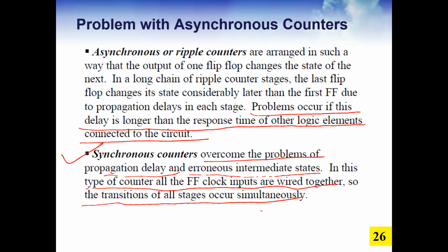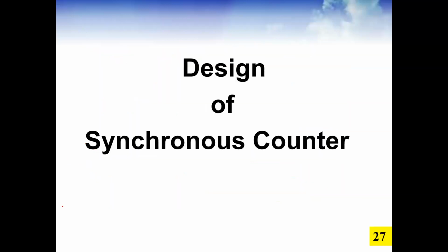Okay, next. In a synchronous counter, we are going to use a common clock for all the flip-flops, not like here, where only one flip-flop gets the clock and the next one's clock is the output of the previous stage. So the design of synchronous counters, guys, is actually very much similar to chapter number 5, design of synchronous circuits. Exactly the same, with a minor change, which you will see now. What is the change? I will explain.